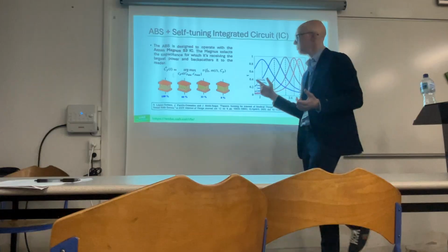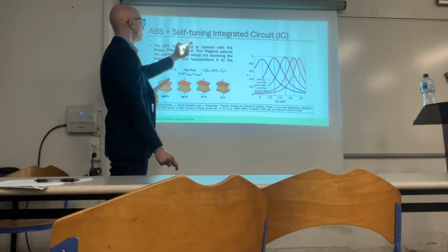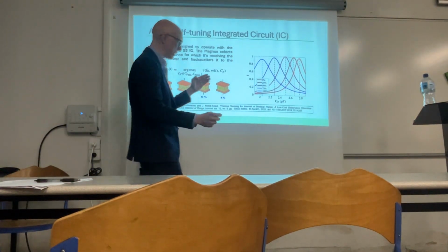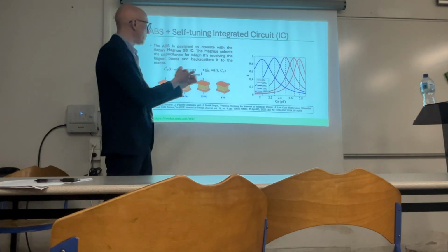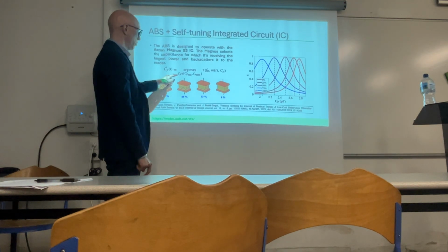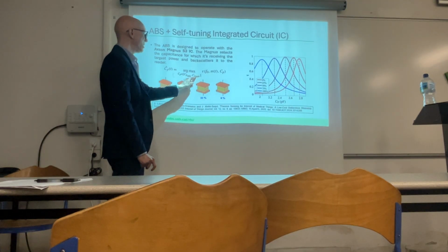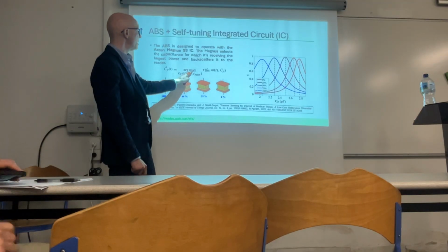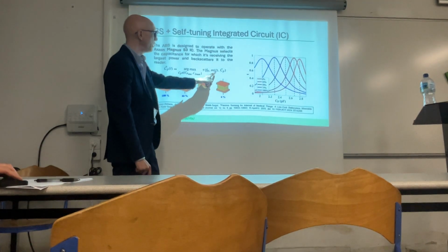So we're using Axzon Magnus S3, and the self-tuning integrated circuit selects the capacitance. It has a range of operating capacitance, and it will select the capacitance for which it receives the maximum amount of power. So this can be expressed according to this formula, which says that the selected capacitance, in the operating range of the microchip, is the one that maximizes the power transmission coefficient for a specific frequency and for a specific water mass in the absorbent.